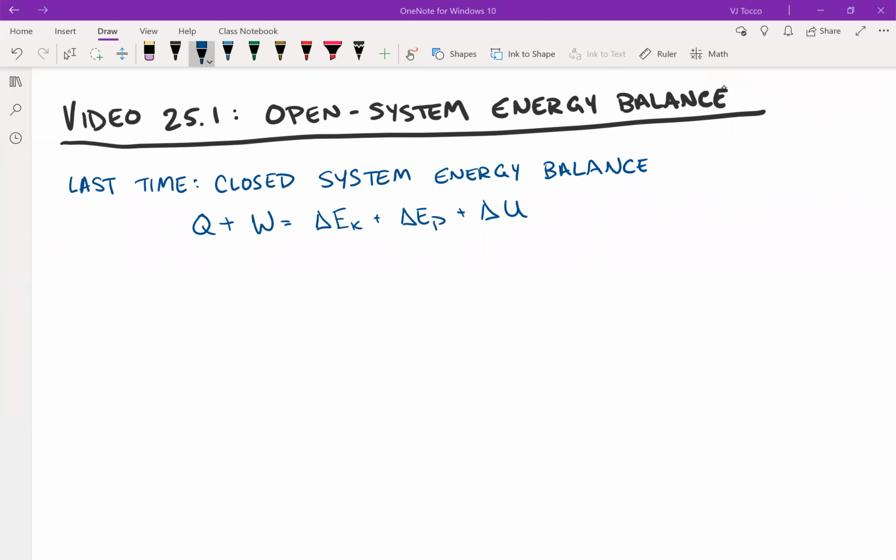This material energy balances video is about the open system energy balance. Last time we talked about the closed system energy balance. And recall, what determines whether or not a system is open or closed is whether or not material streams are crossing the boundaries. So in a closed system, I don't have any streams flowing in or any streams flowing out, and the energy balance can be expressed with this equation.